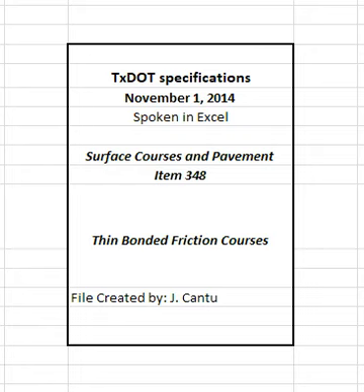2.1.2 Fine aggregate. Fine aggregates consist of manufactured sands and screenings. Fine aggregate stockpiles must meet the gradation requirements in Table 2. Supply fine aggregates that are free from organic impurities. The engineer may test the fine aggregate in accordance with Tex-408-A to verify the material is free from organic impurities. Do not use field sand or other uncrushed fine aggregate. Use fine aggregate from coarse aggregate sources that meet the requirements shown in Table 1 unless otherwise approved.